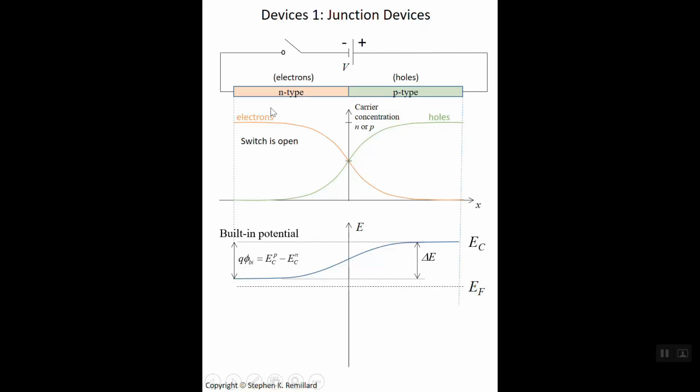For that same reason that I just mentioned, when an electron moves into the P-type, it encounters all of those negative acceptor dopants, and it finds itself being repelled back to the N-type. And so there's an energetically favorable region for electrons. And conversely, your holes are energetically favorable on the right. When an electron is on the right, it's energetically unfavorable.